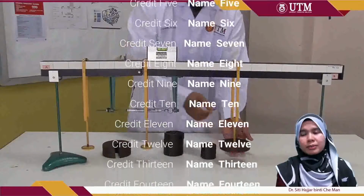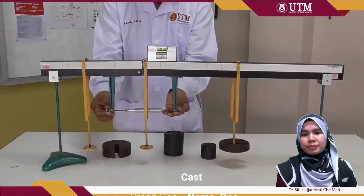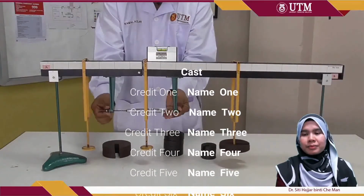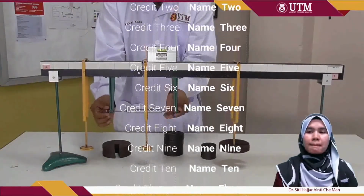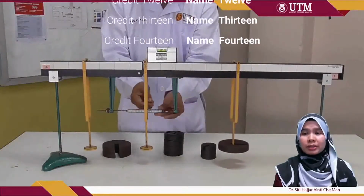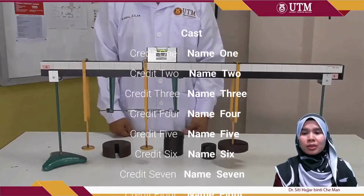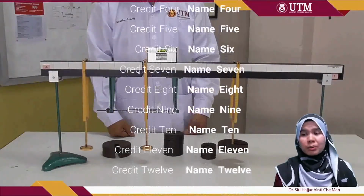Again, realign the spring balance and take the reading. Now we have completed the set of readings for the 10 Newton weight. You can repeat the procedure using the 20 Newton weight as required in table 1.